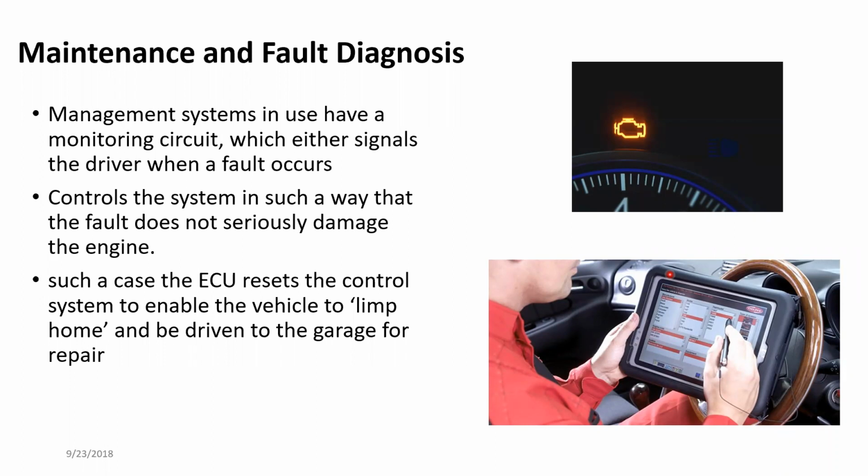That code does not mean you just have to replace the engine RPM reader or speed sensor right away. That's not going to help anyway. There are other steps you have to go through. One of the main things is you have to check everything around it, like power outputs, voltage inputs, voltage outputs, wirings and everything before you replace it.